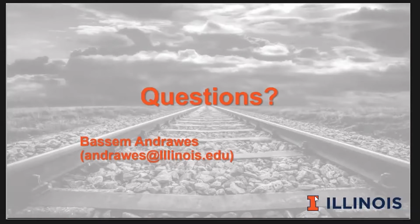Question in the back, yes. Have you measured your camber with increasing...? The camber, we have not. We have not measured the camber, but we're not expecting a lot of change. Well, the pre-stress losses will affect the camber. That's a question that we will probably do with the full-scale prototype, but we have not done any full-scale measurements of that yet. But that's a good point.